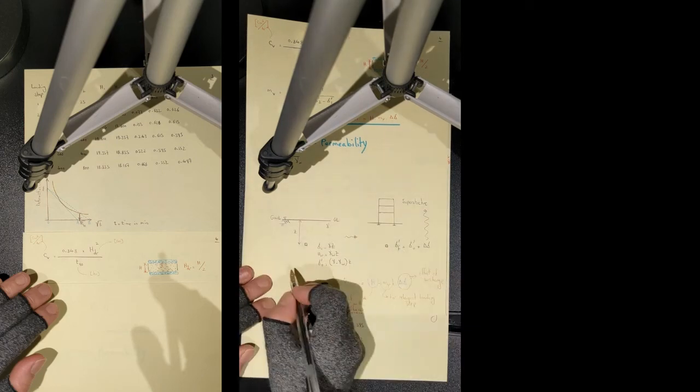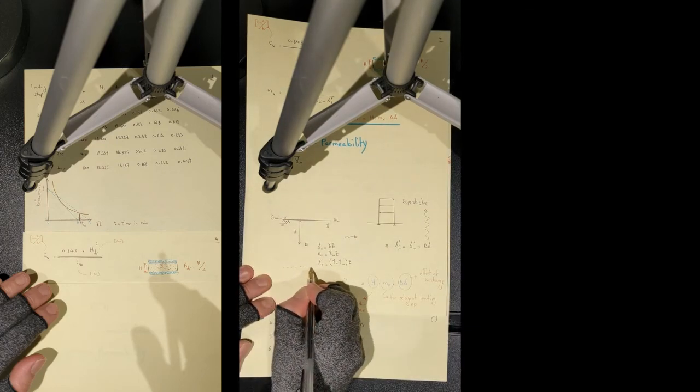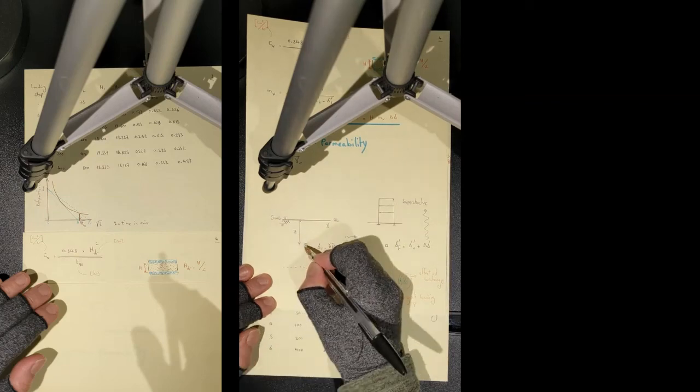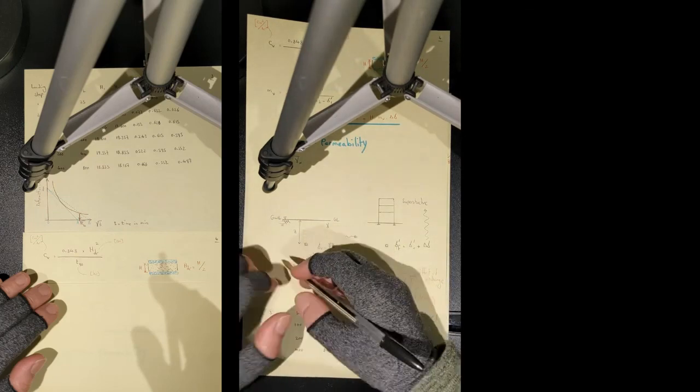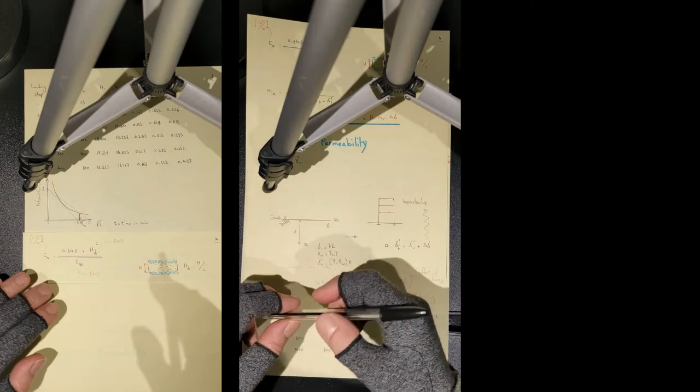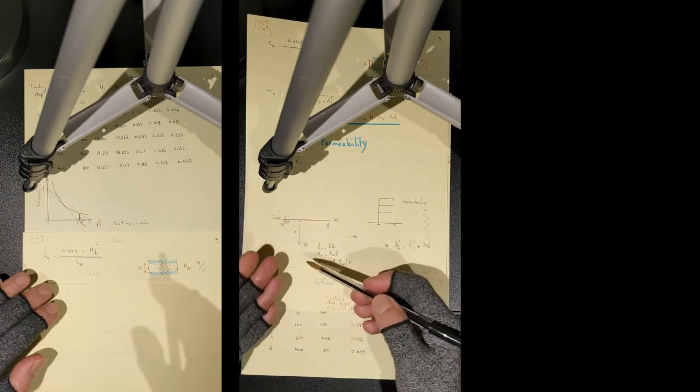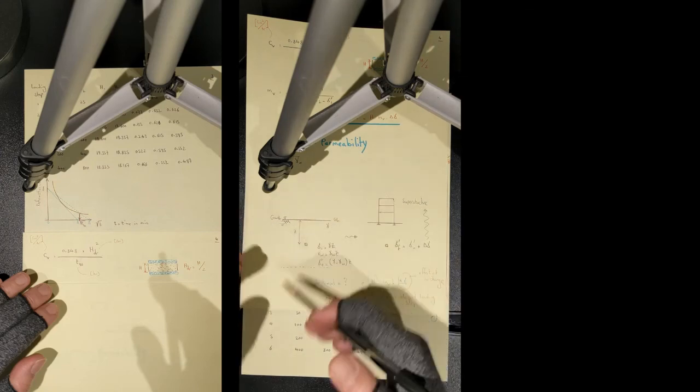So you have a clay layer, and you have chosen the middle of your clay layer to calculate the consolidation parameters. And it's in the middle, so it kind of represents the entire layer. You've got a layer of clay, you have chosen the middle, and you are determining all these consolidation parameters for the middle.